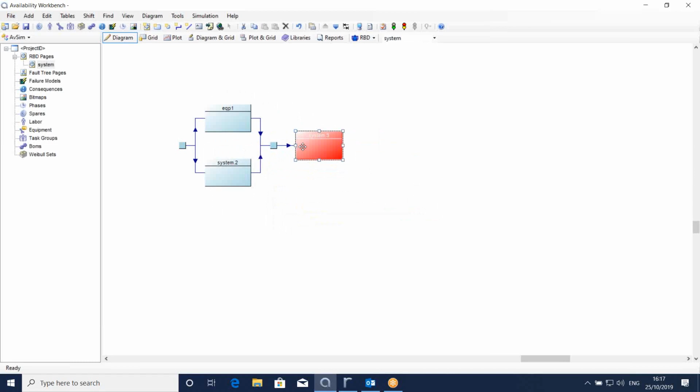It's worth remembering that the program is not modeling any kind of process or flow of product. This isn't intended to represent the actual way your system is connected together, although oftentimes it will look a lot like that. This just represents the logical relationship from a reliability perspective. In this case, it's very simple. Just parallel for redundancy, series for bottlenecks, for trains of equipment.